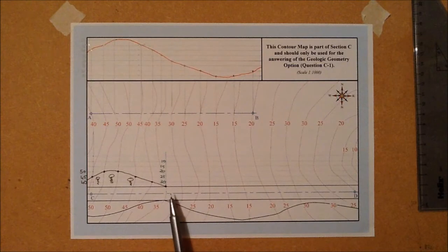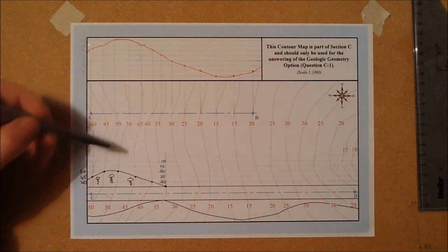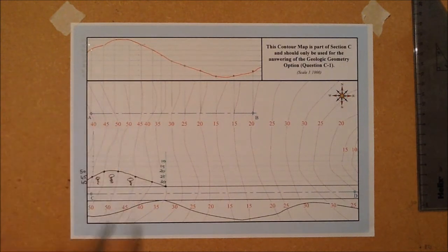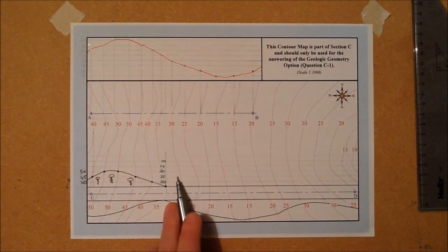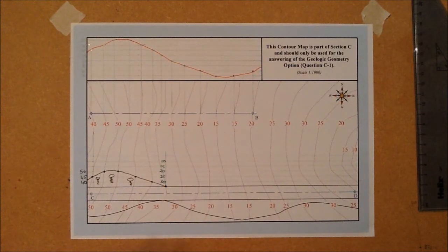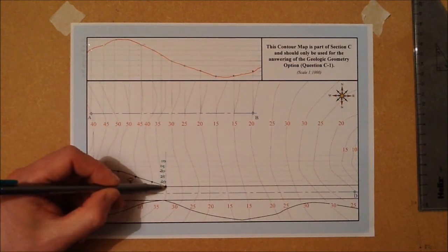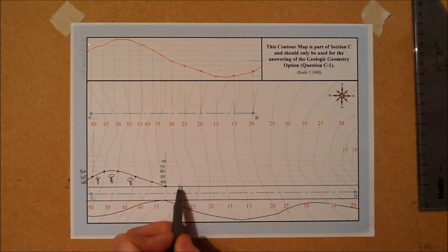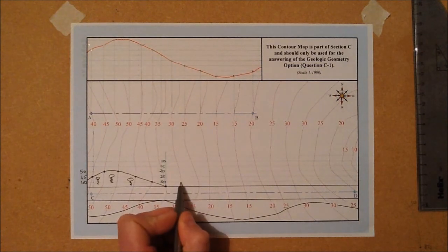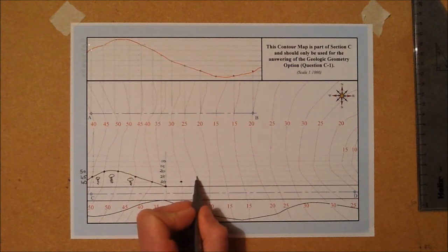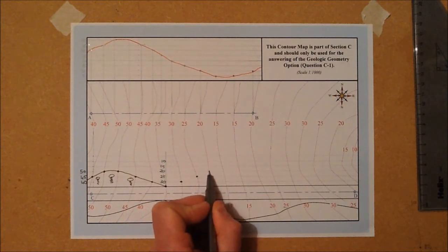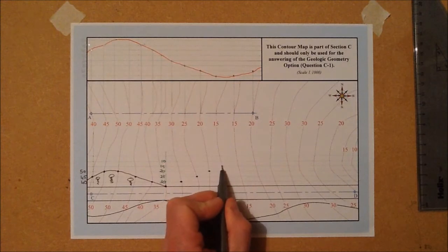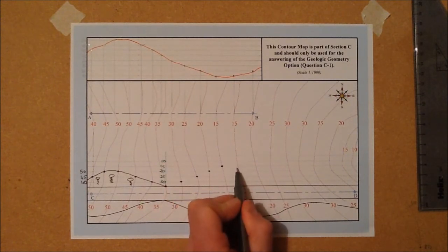Once we have the altitudes determined, we follow our contours and see exactly where they intersect with the corresponding heights as I've drawn in here. I'm going to start off here. We know this one is at 35 meters. Moving on to the next contour line of 30 meters, we'll follow that in until it hits the corresponding height here that runs parallel to the road, and so on. We move on to the next one, which is 25, 20, 15, and we carry on right through until we plot all of those points.